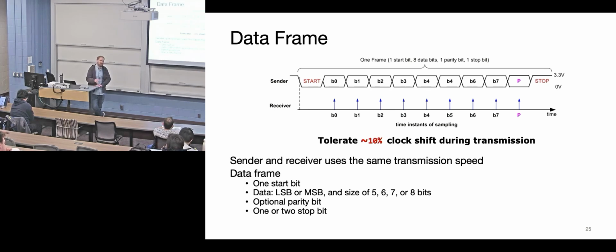Is there more connotation to what you mean by blindly? I guess it uses a starting bit to figure out where rising and falling is, so it takes the halfway point. Yep, that's what I meant. There's no clock in this protocol, which is nice because then you don't have to have an extra wire for a clock. So we can get away with 2 wires plus ground.